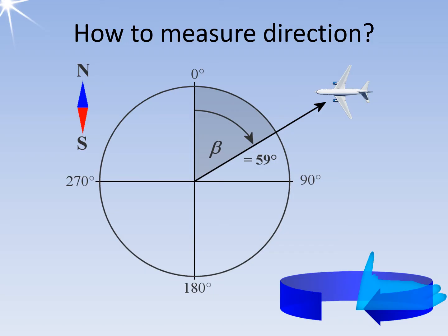Bearing angles are transmitted by angular transmission from the antenna to the display unit or the computer. Older systems use rotary encoders and servo motors, while newer systems use encoders that divide the full circle of 360 degrees into up to 2 to the power of 14 equals 16,384 individual steps. This corresponds to an accuracy of 0.022 degrees.